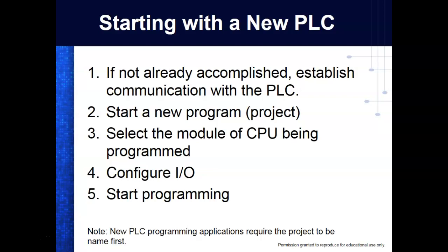So the 1100 supports a communication protocol called DH485, and then it also supports what we technically call Ethernet IP. Siemens calls it Profinet. So those are basically exactly the same thing. The 1000 only supports the DH485. But you still have to do the configuration, so we're going to show y'all how to do that.